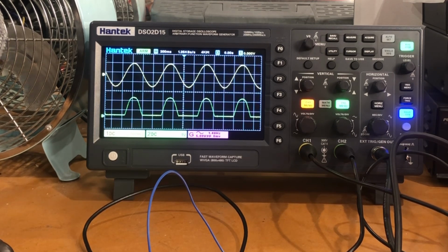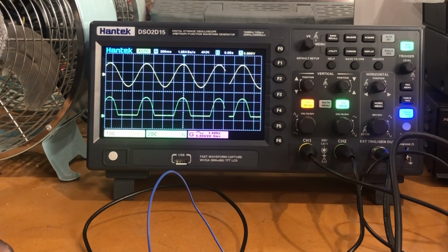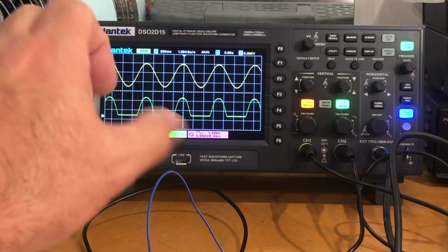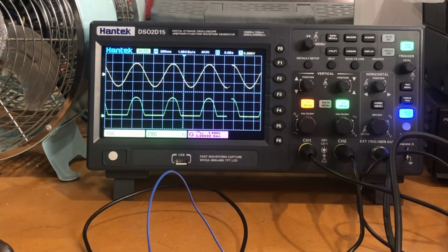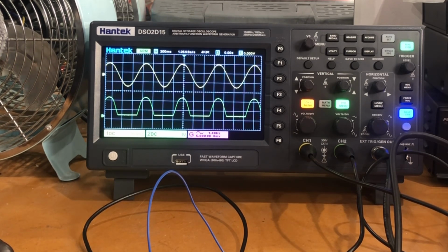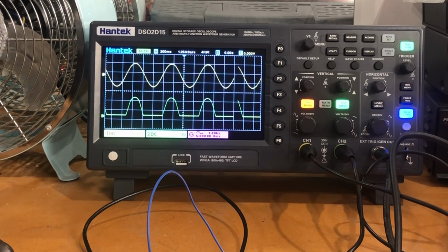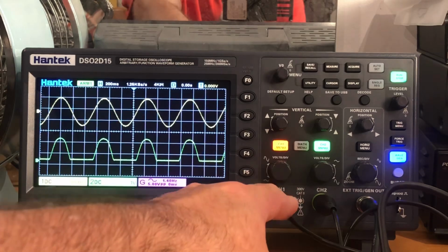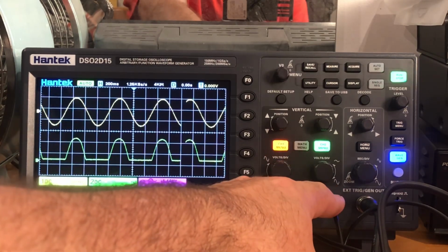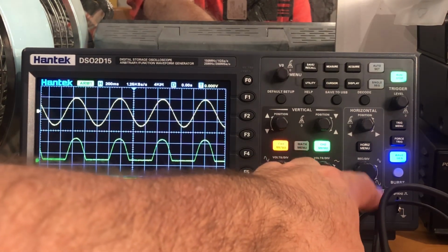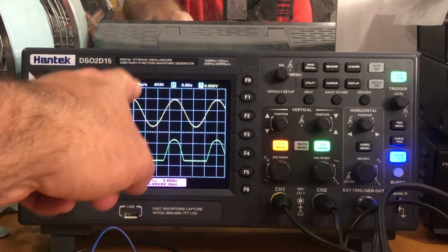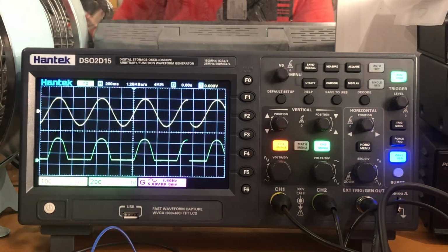Now this signal that you're seeing fed in is actually being generated by the digital storage oscilloscope, because this DSO also has an arbitrary function waveform generator, a fancy way of saying a signal generator. It can generate various types of waveforms, triangular, square, and in this case, a sinusoidal sine wave. So we have channel 1 coming out here, channel 2, and our waveform generator, which is generating the sinusoidal waveform at 1.4 hertz that you can see there.